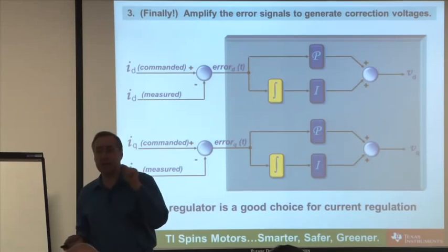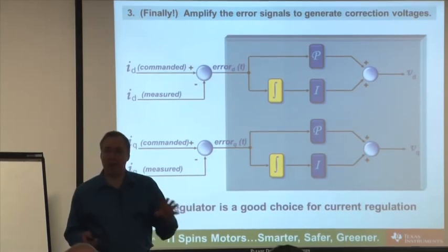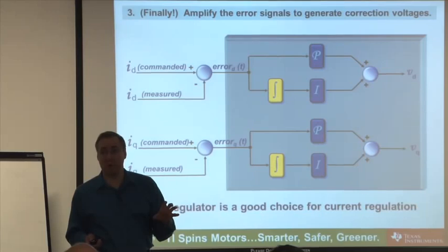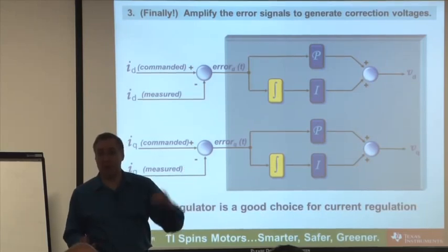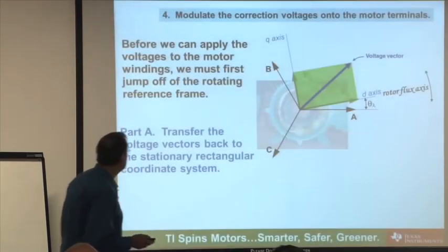For permanent magnet, non-salient machines, they're the same. But if you have magnetic saliency in your system, like a special type of motor called an IPM motor, then no, you have to put different coefficients on both those axes. That is a good question. In fact, I didn't even really know the answer until recently, when I started fooling around with this stuff and realized that for certain machines you need to tune them differently for the D and the Q axes.